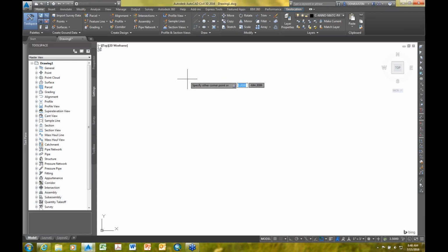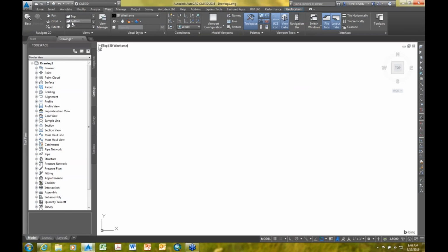Now, you can either just use your mouse the whole time, or there are written commands to engage all of the different icons. If I hit D, it's going to allow me to type in dimensions, so I want specific dimensions for this rectangle, and we'll just do 10 by 10, and it's going to ask me where that is going to be, and you can't see it because I'm zoomed out here. Let's zoom in.